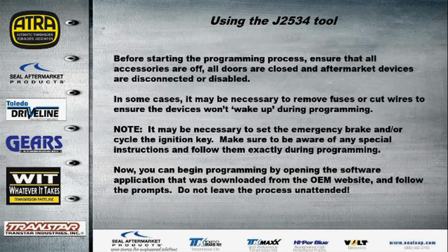Now, before we start programming, everything's all hooked up. We want to make sure that all of our accessories are off, all our doors are closed, all aftermarket devices are disconnected or disabled. We might have to pull fuses for aftermarket installed devices. Just want to make sure that nothing's going to wake up our process here. Nothing's going to cause a module to wake up while we're programming. So also, it might be necessary for us to set the emergency brake in some cases, or cycle the ignition key.